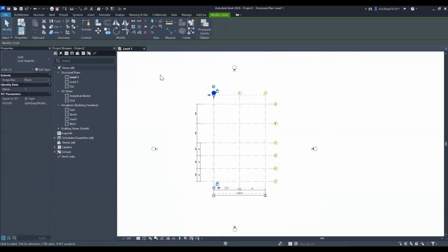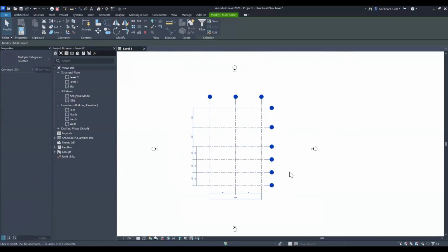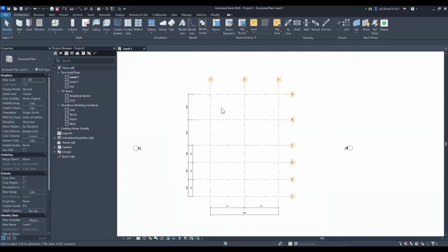And one of the greatest benefits of using this one is, as you know, that once the grid line setup is done, then we assign those circles, lines, text, and dimensions to the annotative scale so that things can come up in a proper size and shape when we change the annotative scale in the viewport, or when we place it in the sheet view.